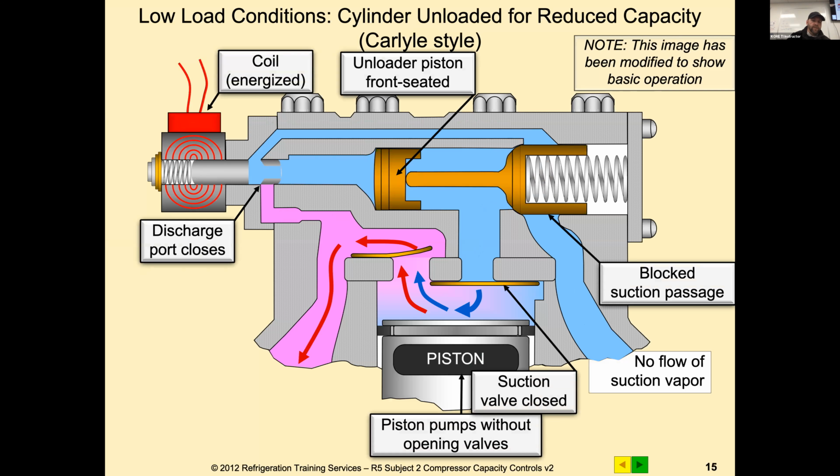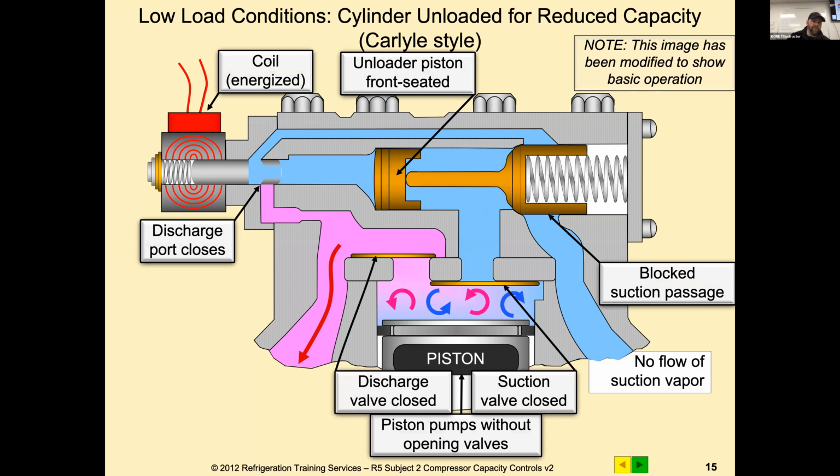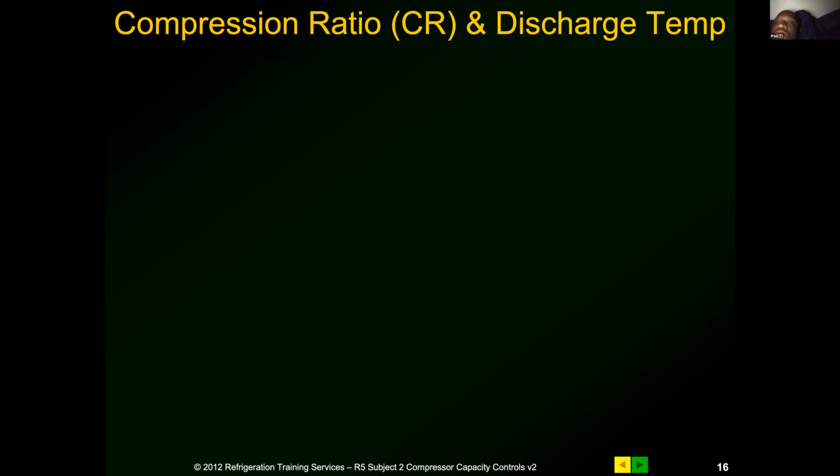So that piston continues to pump. But if there's no pressure on that valve on the suction line, that valve never opens. So that piston just freewheels, not compressing anything while that's energized. When it de-energizes, it loads it back up. Okay. Any other questions?